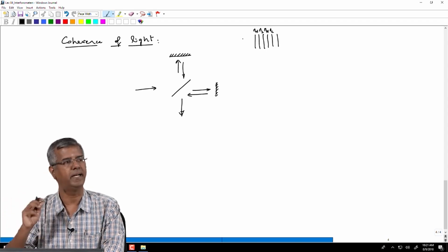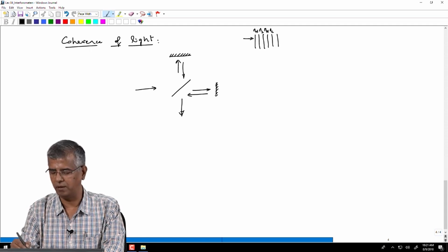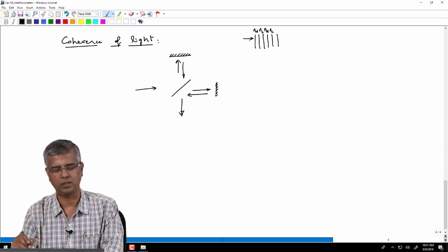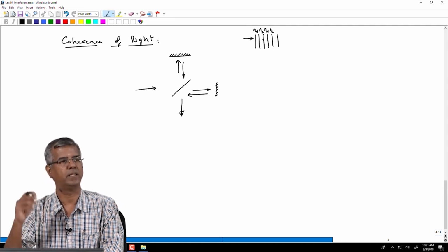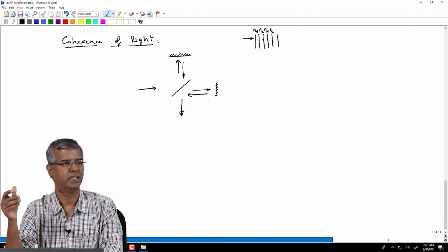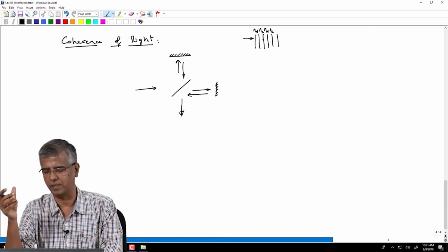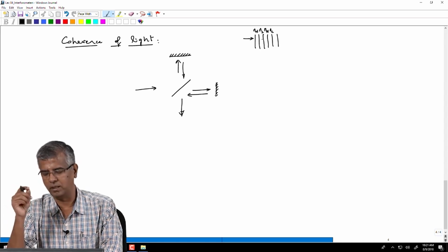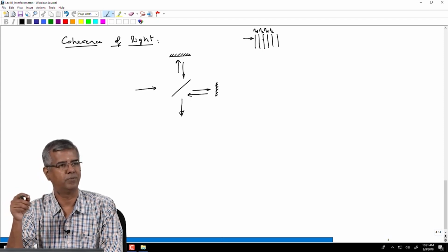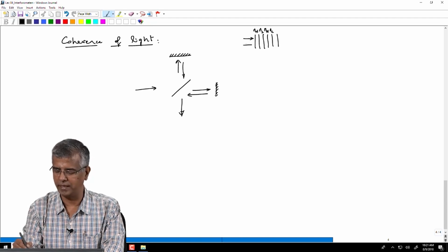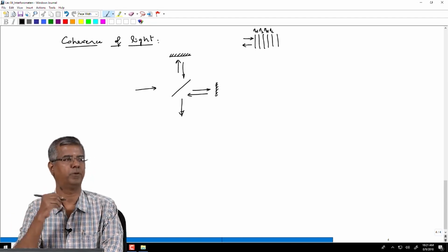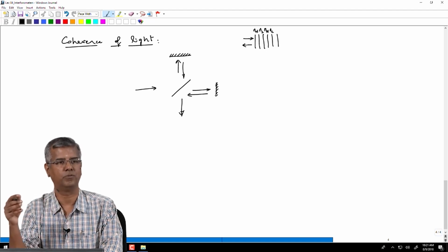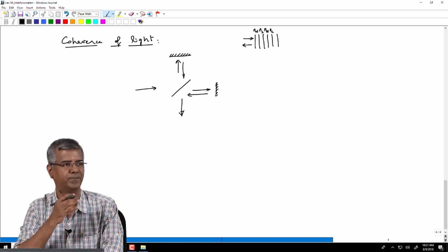If you have alternating layers of that, and a wave is incident on it, it is going to go through reflections at each of those interfaces where the refractive index is different, right. That is what you call Fresnel reflection, and all these components that are reflected, if they are all in phase, will all add up together, and you will get perfect reflection. All the light that is going forward is going to get reflected.